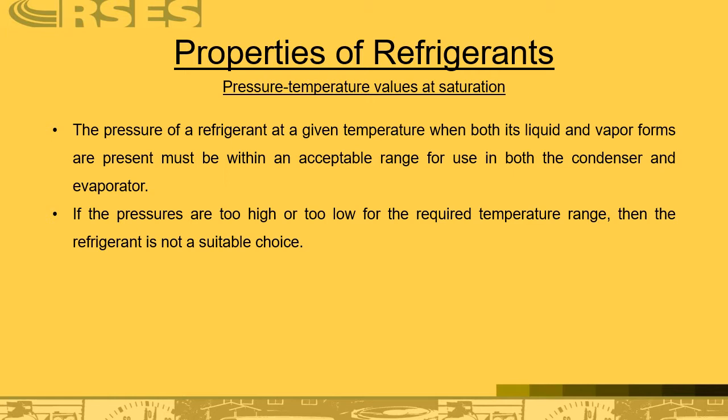Well, the problem with R12 is it's a CFC refrigerant which went away back in 1996, and it was phased out, and 134A replaced it. Some people got the idea, well, why not just put in HCFC R22 in replacing it, since R12 is no longer available?